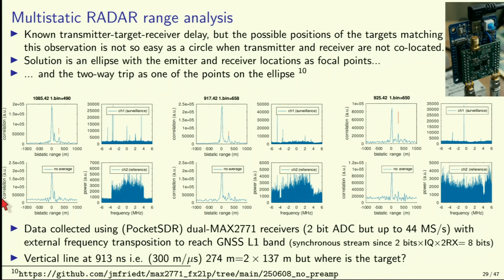So if you run this, you see here, this is a television broadcast channel in the area I live in, Besançon in France. So what I'm doing here is passive radar. I'm using the signal broadcast by a television emitter, and I'm looking at a direct Yagi-Uda antenna facing the emitter, and another Yagi-Uda antenna facing the area I want to detect.